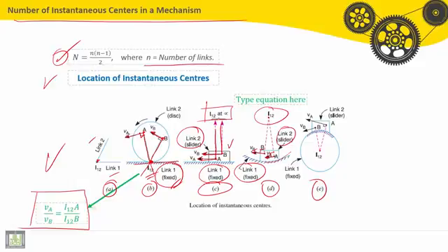Last example. Also, we have a rotational slider, but externally. So the instantaneous center of rotation should be the center of the grounded link here, link number 1. And by the same method, B I12 should be perpendicular to VB, and VA should be perpendicular to A I12.